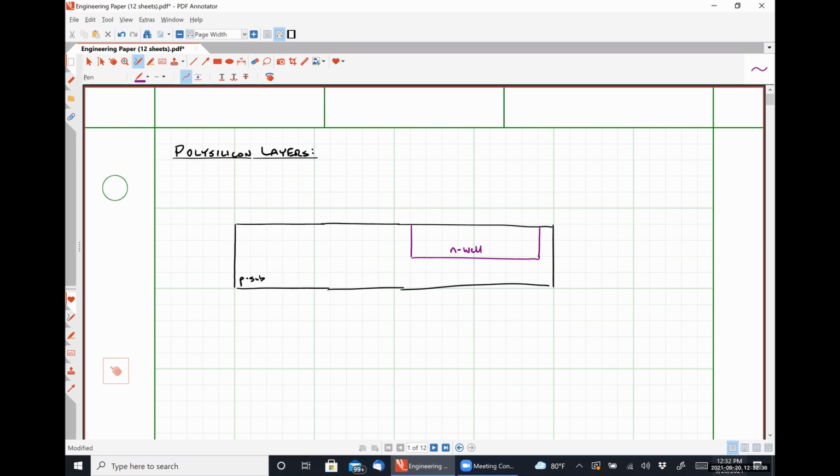And as we learned, that N-well material can be used either as the body of a PMOS transistor, or it can be used as a resistor. But when used as a resistor, we actually kind of have to treat it like an RC network. Okay. So the next layer that would be fabricated for a CMOS integrated circuit would be the application of a gate oxide.